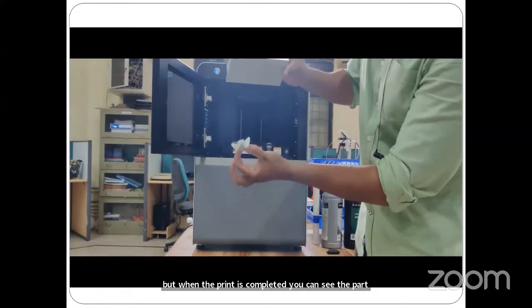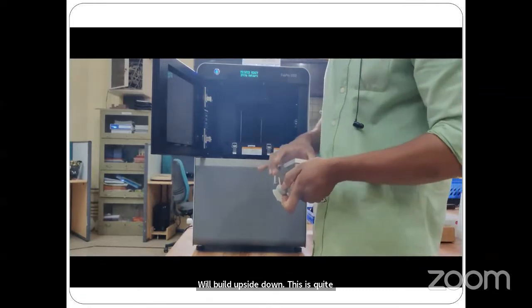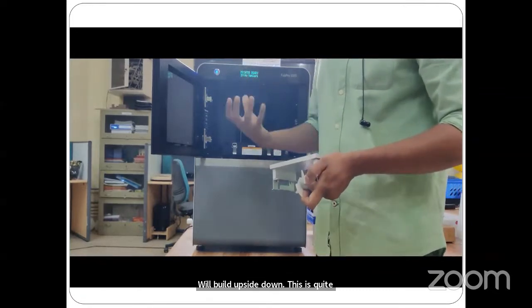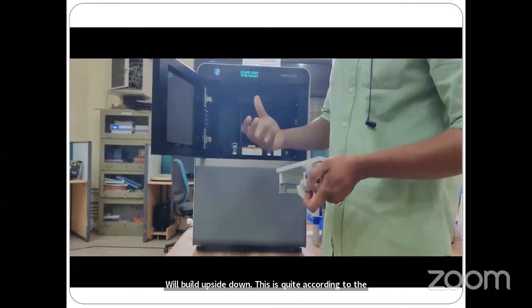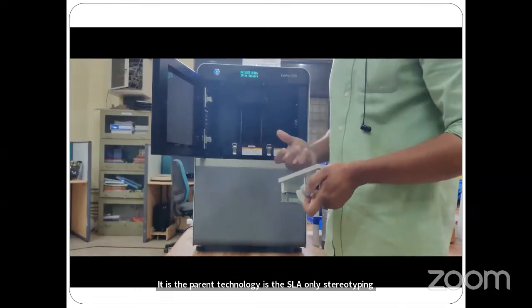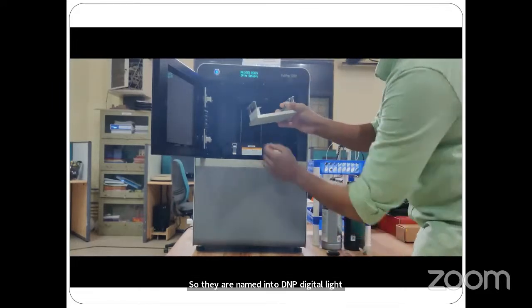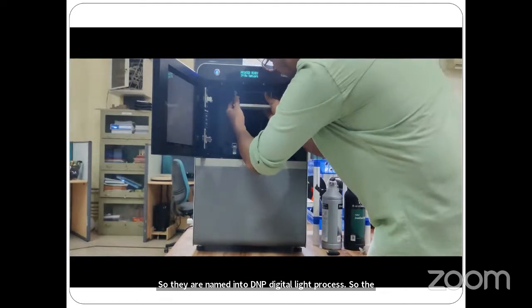So it will build upside down. This is quite opposite to the SLA technology. The parent technology is SLA only, stereolithography, but it works in a different manner, so they have named it DLP, digital light processing. The bed has to be fixed here on the top like this, upside down.